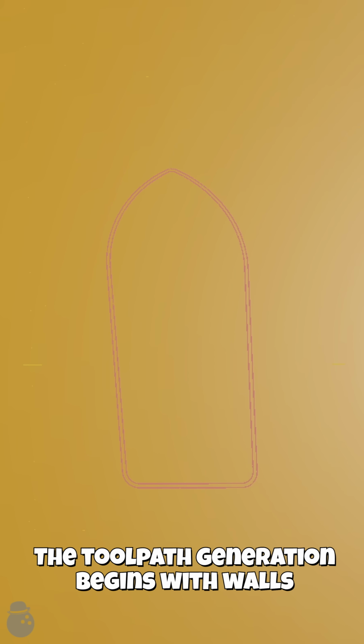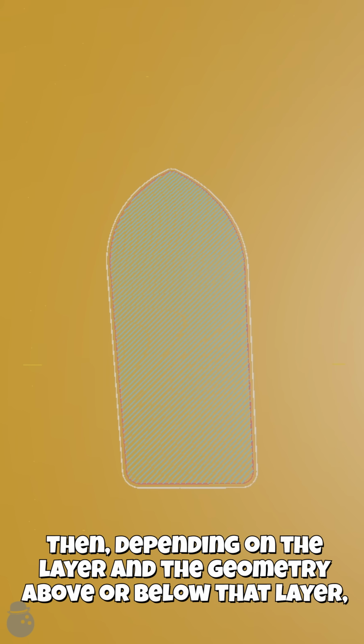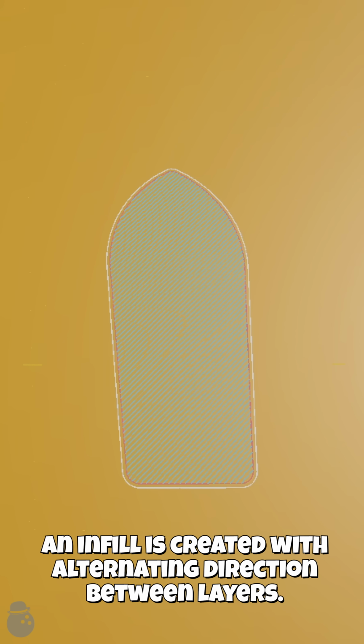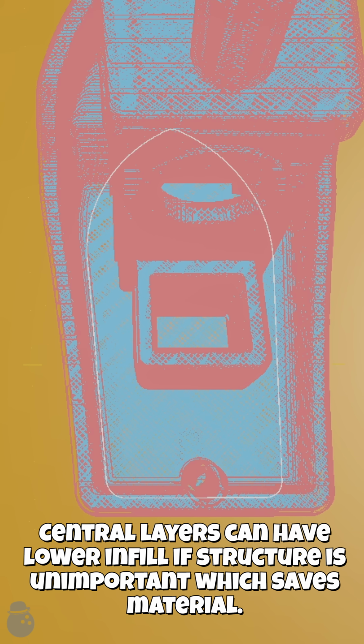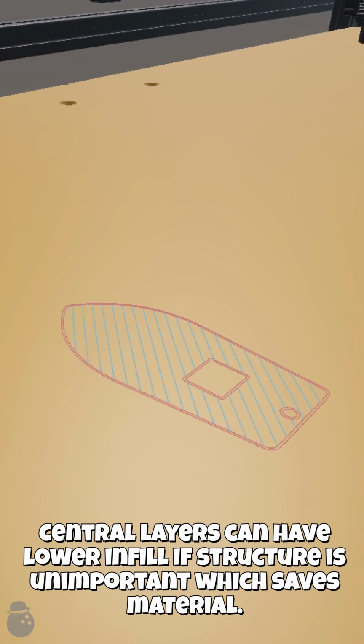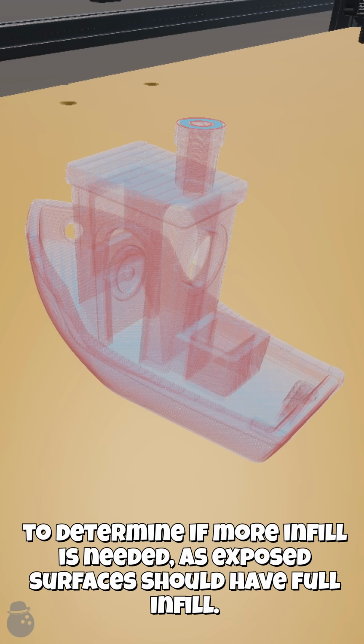The toolpath generation begins with walls, which begin on the sliced edges and are offset inwards. Then, depending on the layer and the geometry above or below that layer, an infill is created with alternating directions between layers. Central layers can have lower infill if structure is unimportant, which saves material. As the toolpaths build, they are cognizant of the geometry above and below them to determine if more infill is needed, as exposed surfaces should have full infill.